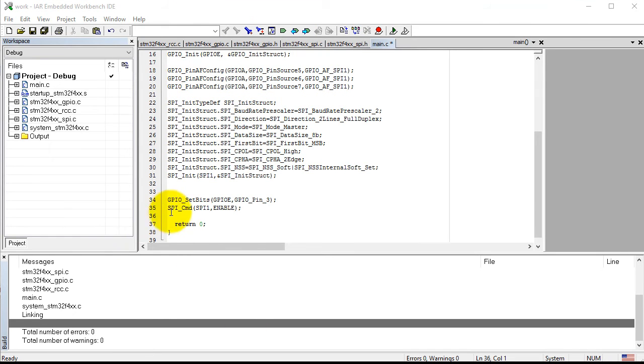The final part, the initialization process, must send to the accelerometer the desired parameters for its 58 registers. We may leave most of them in the default state, but it is mandatory to send a certain command to the control register 4, as we shall see.